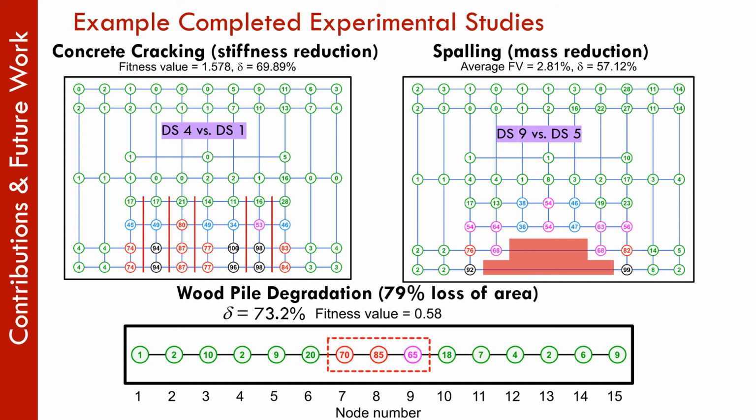Over on the upper right, we now took a demolition drill and knocked out blocks of the structure, about half the depth. So what we have in this red shaded area are lost mass locations, and around that is where we indicated damage from the sensing. It was very nice to see that the noise on the outside was pretty small, except in one location where it's 27%, but that would still reduce the number of areas that the inspector would look at.